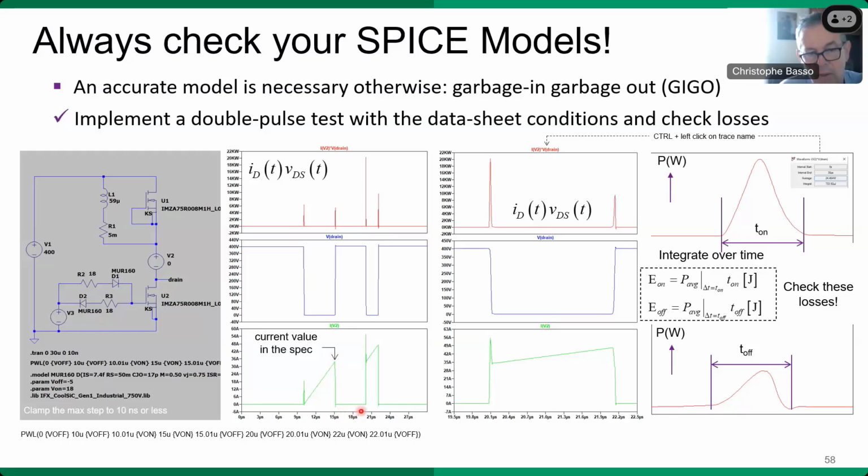And then you wait a little bit, and then you restart the power switch on the low side, while this guy here is actually recovering. Okay, it's like in a PFC stage. When you interrupt the current, the inductance is going to freewheel in that mesh, and then suddenly you force the blocking of the upper side diode. It's a hard switching operation, and then you have a big spike here because this guy is a very brief short circuit until it recovers its blocking capability, and during that time you have a loss.